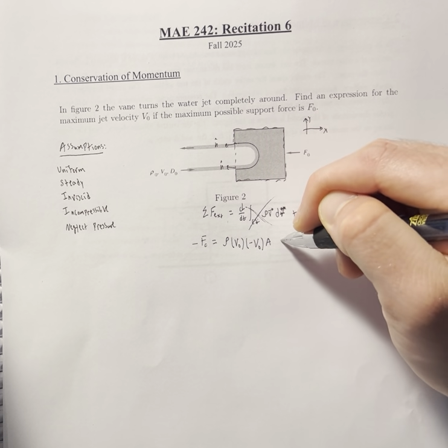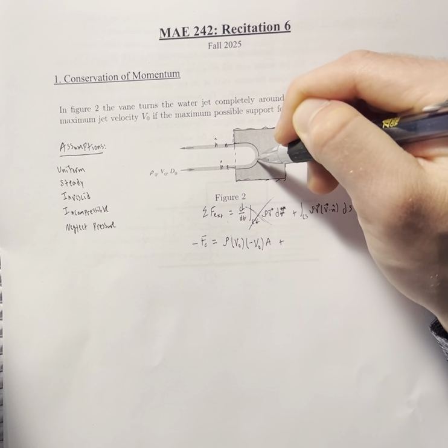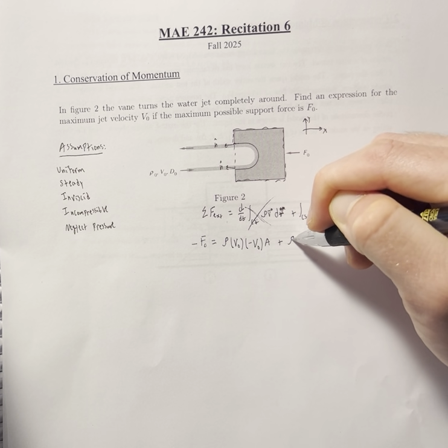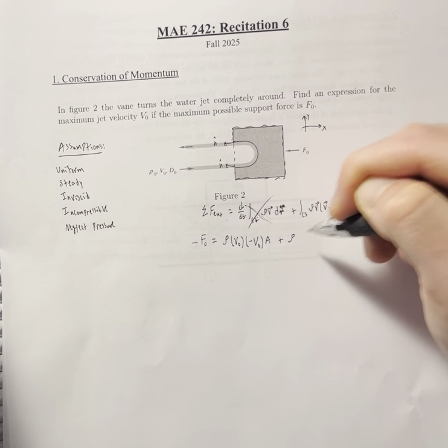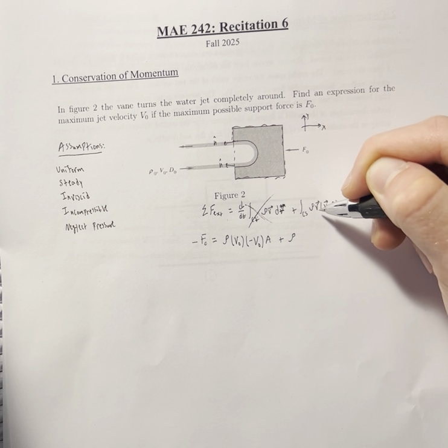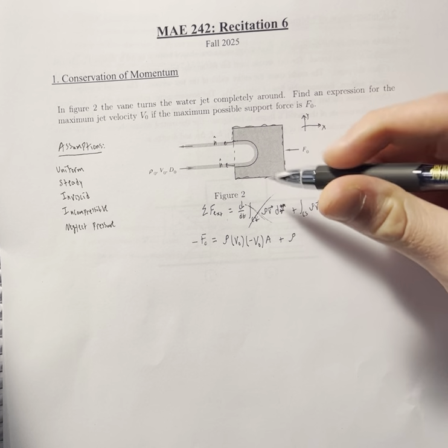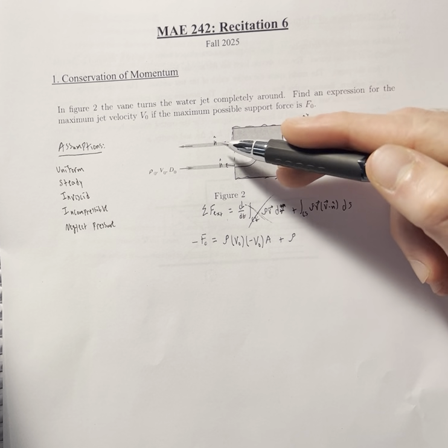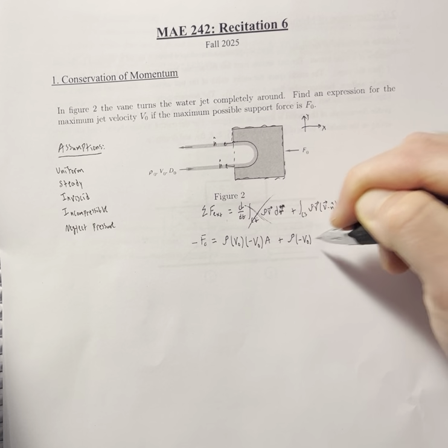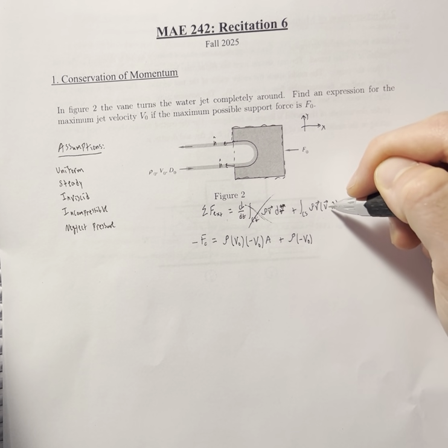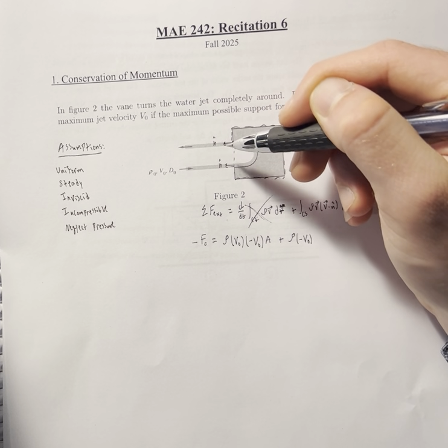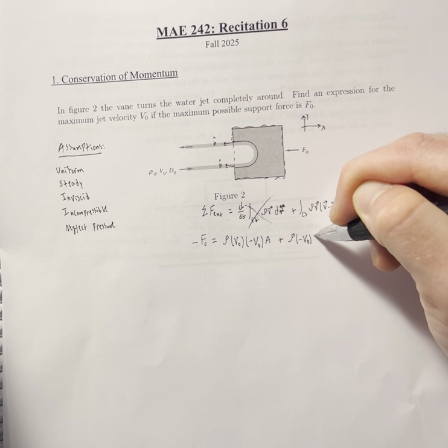Now let's go back up top. Came up through here. Now it's going out. So again, we have density, which is constant. That's still fine. Now again, this first v is actually where that velocity vector is going. So now, in the case of up here, it's going in the negative x direction. So we have a negative v naught. And then similarly, let's look at this v dot n. The velocity vector and the normal vector are in this exact same direction. So when you dot it, you get a positive 1, right?